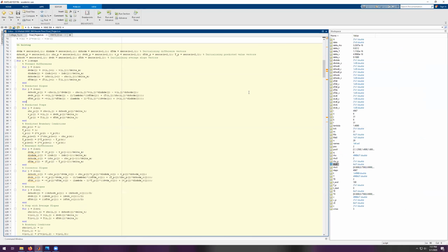So getting into the actual MacCormack method and solving this, we create a bunch of vectors that just are there as placeholders for now to keep the simulation from getting angry, because I start at x equals 2 because I can't calculate the points at the boundaries.